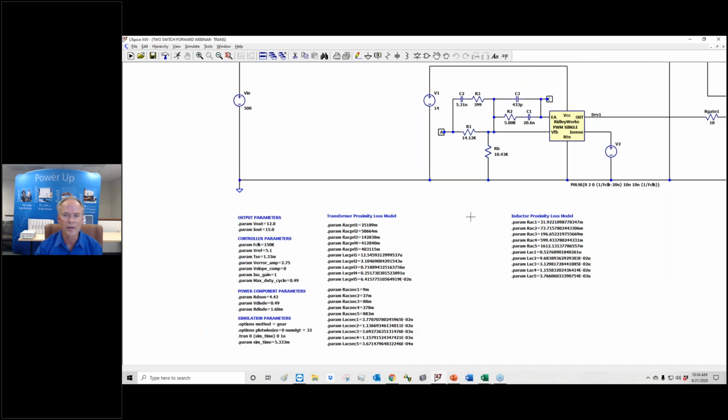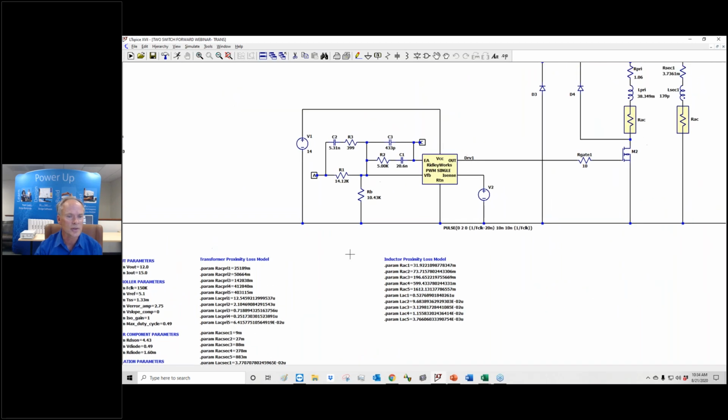And I have a lot of thanks here to give to Art Nace, who facilitated this transfer. Believe me how important this step is. We didn't derive these models first, somebody else did. But the step of looking at the winding structure, clicking a button, and putting the circuit models, the elements, into LTspice with no work on your own is huge. Because if you have to type these in individually, you're just not going to do it. We're all too busy. We've got circuits to build. Okay, so it's dumped the models into here for us.